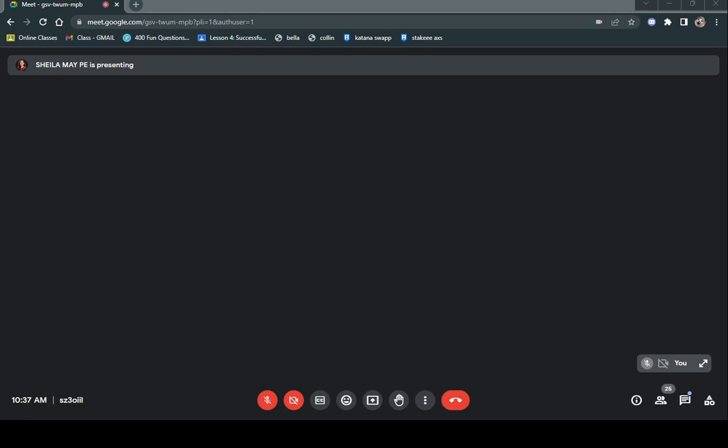The silicon dioxide layer is still present, and that layer insulates our gate from our P-type substrate. The silicon dioxide layer is still present to isolate the gate metallic platform from the region between the drain and the source. But now it is simply separated from a section of P-type material.